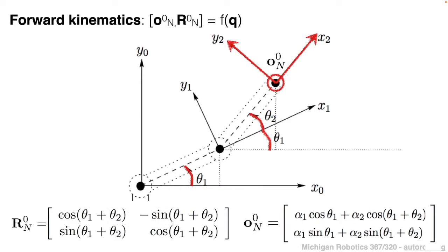I won't step through each of those calculations, but essentially the terms here with alpha 2 represent the matrix-vector multiplication from that last slide. Those two matrix multiplies, basically the dot products within the matrix multiply, are what result in these two alpha 2 terms, and then the alpha 1 terms are what's left from that final addition of the translation vector that we had from link 1.